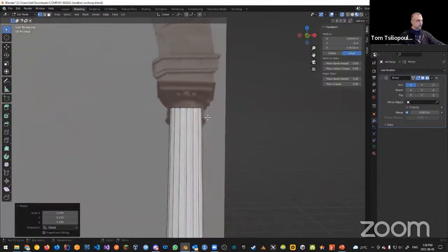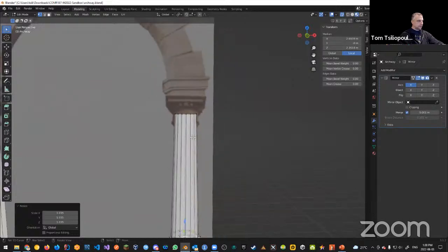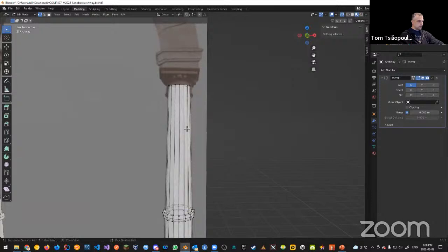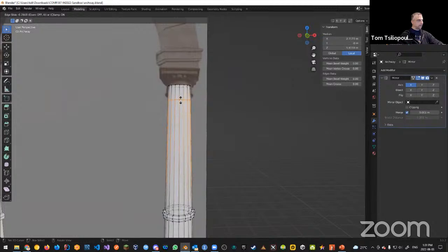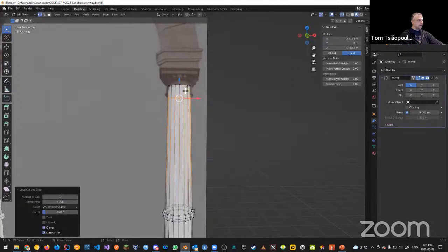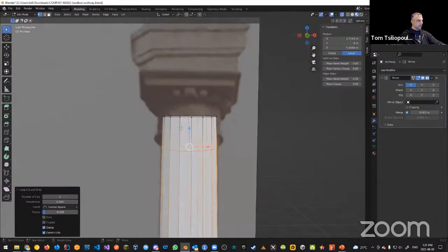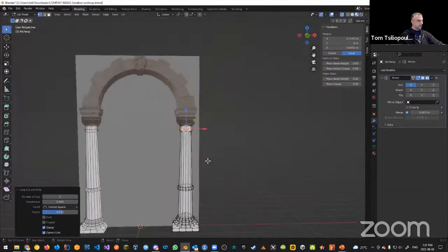So as we go through here, we can think about what to do that's different. Here I want to make the same detail right near the top. I can deselect all first, and do a Control R, which brings me a ring in the middle, and then I can just move it up so it's at the bottom of this part. Then I zoom into this part up here and make another ring in the middle, Control R, right? And we can zoom it where we feel it's best, something like this at the top. Maybe something like this, and you can see that's where it's going to go.